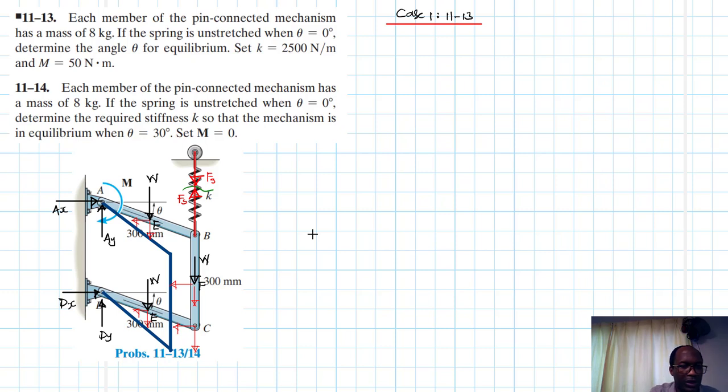So I think this is, and then at this point we have another movement at this particular point, like so. Okay, so let's label these. I'll just label those that are going to give us virtual work. They must have virtual work collinear to a force. So this one we're going to label as del YF.